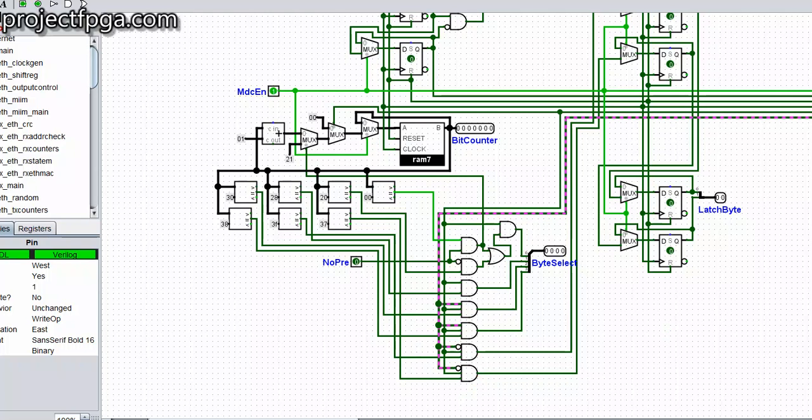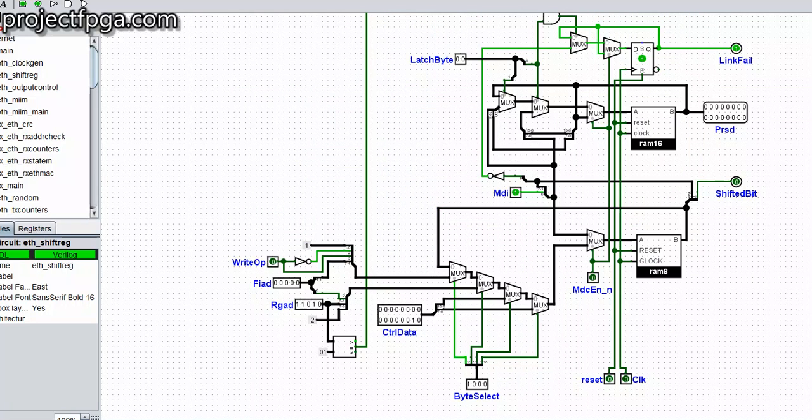So let's see them in practice here. That's essentially what it's doing here. So after preamble, that is from 0 to 32, turn on this one, that is this bit here. Then after another 8 count, at 40, turn this one on, then at 48, turn this one on. So what it is essentially doing is receiving this data 8 bits by 8 bits.